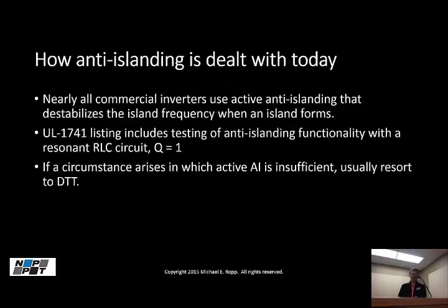How do we deal with anti-islanding today? Well, I mentioned this, that almost all commercial inverters, not all, almost all, use active anti-islanding with some form of positive feedback in it. And when they use that, they are very effective in determining when an island is formed because they destabilize that island.